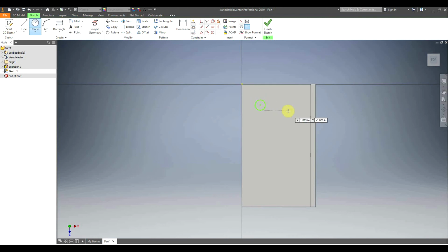We're going to click here, drag it out, here, drag it out, down here, and if you notice those dots, if you tend to line up the mouse with other edges of things or centers of circles, they snap as well. So after those are down, let's go to dimension, do a 1/2 inch hole, enter, and we're going to go to equals.